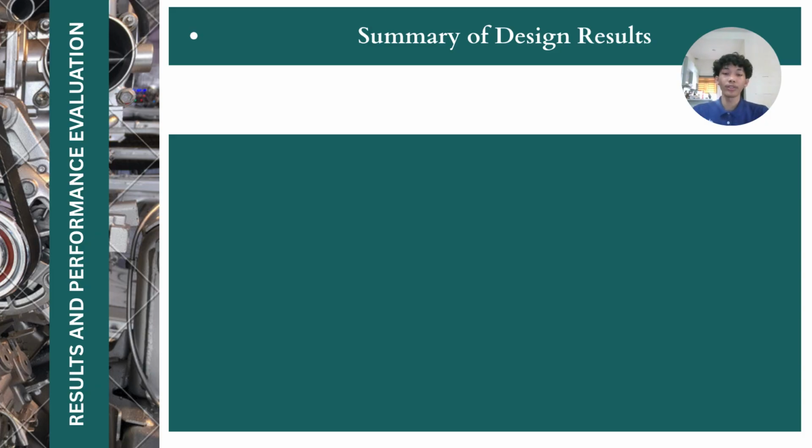The pump successfully achieved the required flow rate of 0.573 cubic meter per second with a flow velocity of 11.67 meter per second. The calculated Reynolds number is 2.92 times 10 to the power of 6, which indicates that the flow inside the pipe is fully turbulent. The major head loss is 16.64 meters, resulting in a total pump head requirement of 31.64 meters.